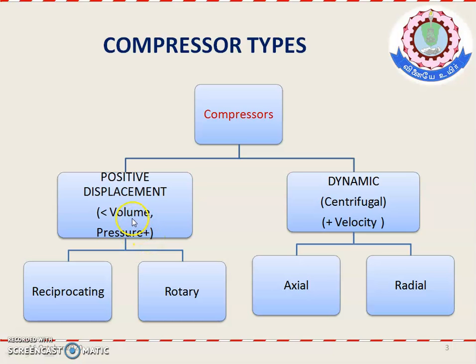That is the basic principle. Whereas in the dynamic compressors, which will be called the centrifugal compressor, the velocity of the working fluid is increased, and thereby the pressure increases. So that is the difference between these two compressors.